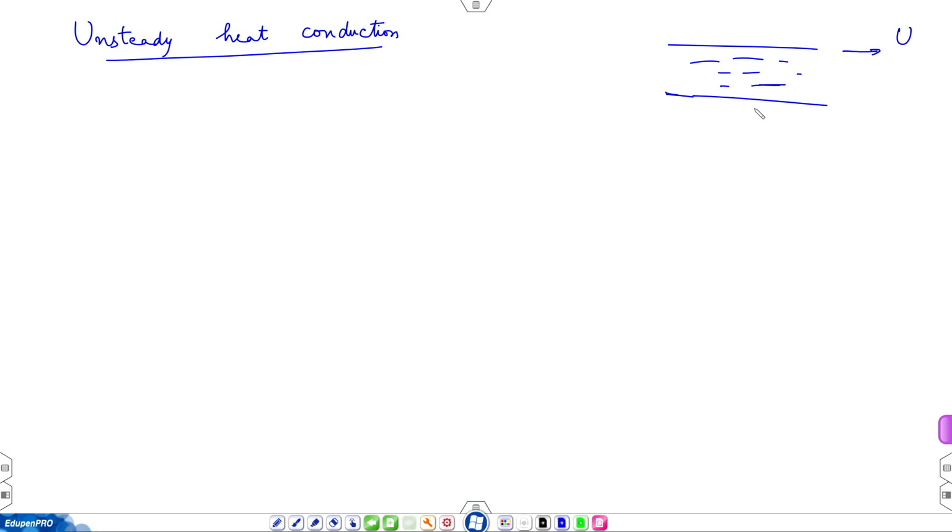Here you remember that it takes a certain amount of time. For Couette flow, the unsteady part will last for a time. You remember the time constant, which depends on this gap. If H is the opening, the unsteadiness will prevail for a time duration given by a time constant.